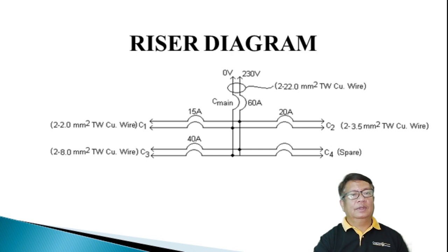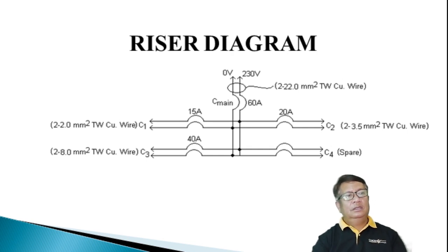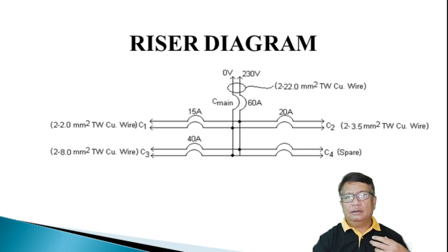Okay, so the next thing that you're going to do is try to draw your riser diagram. You cannot appreciate this more if you will be designing a residential or small building. But of course, in a high-rise building, you can appreciate the importance of this riser diagram, because this is where you can find the location of the panel boards for a specific floor of the building.